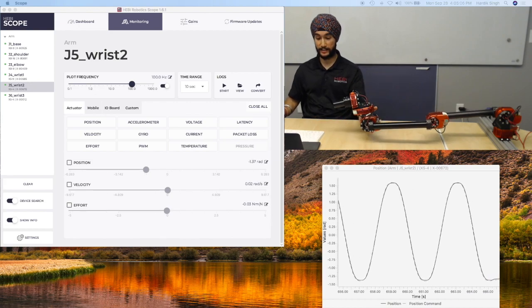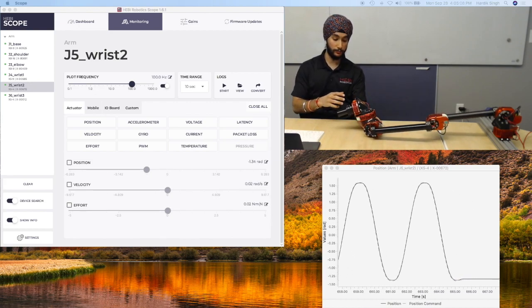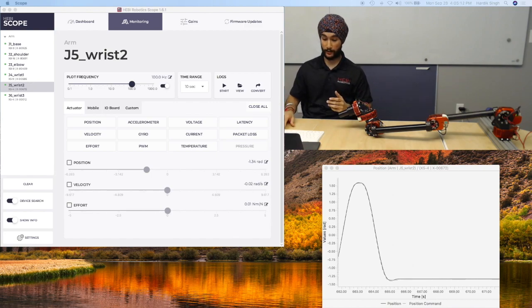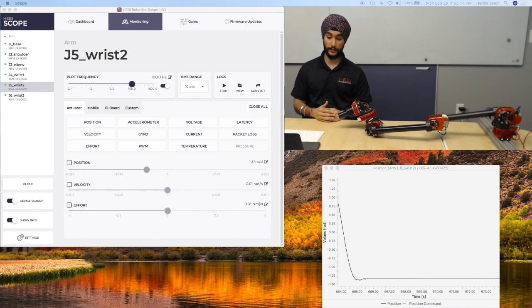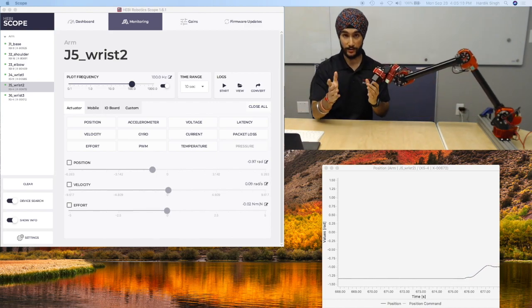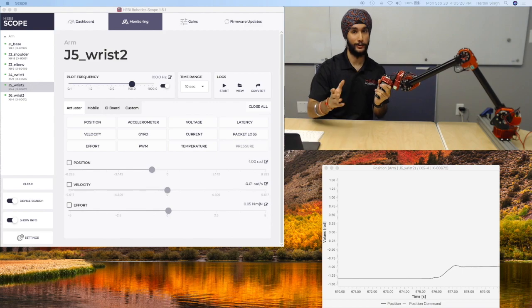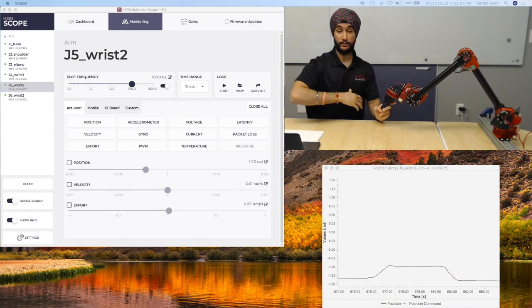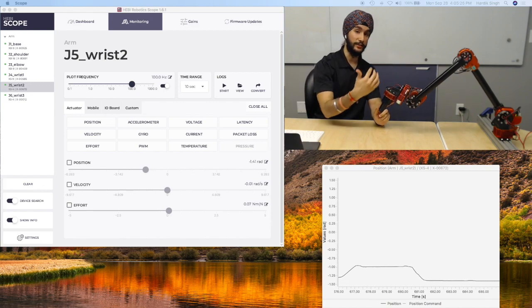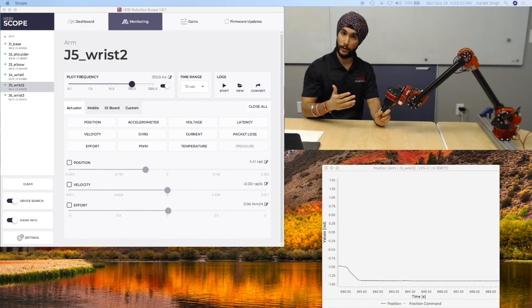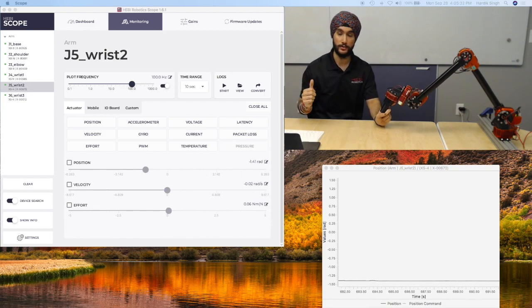Finally, I can show this for the entire system. So I'm going to run this same code again. But this time, I'm not going to restrict it to just one joint. In another video, we talk about how there are benefits of joint level control. And here we're going to see those benefits in action, even though you can head over to that video to learn about those benefits. We are creating that same trajectory profile for each and every one of these joints at an individual level. And that allows us to get far smoother motion. And again, far more predictable motion.